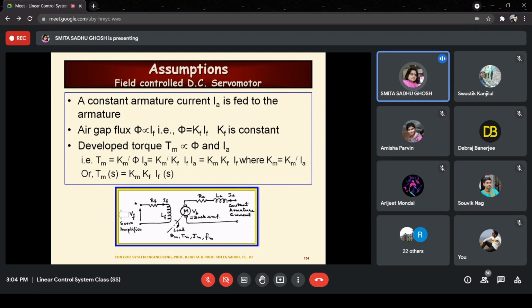So basically, in this particular DC servo motor, the output of interest would be theta m or its derivatives. If you write the transfer function taking theta m as the output, that's going to serve the purpose. And if it is theta m dot, naturally another s will be included somewhere or taken out. So either position or velocity would be the output. In this case, we are considering the load position, or rather the motor shaft position, as the output, right?